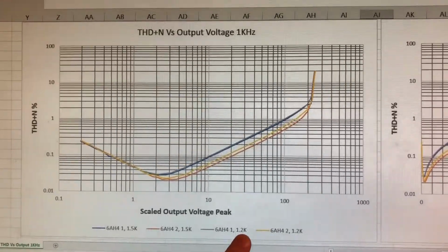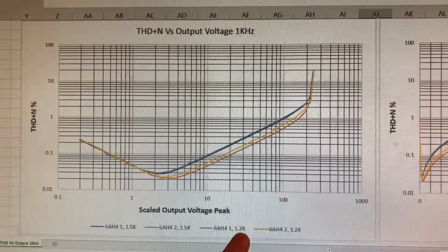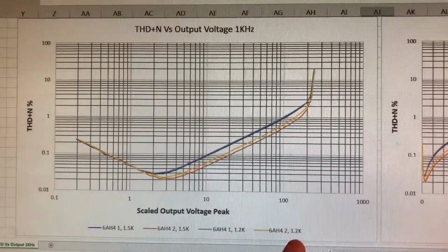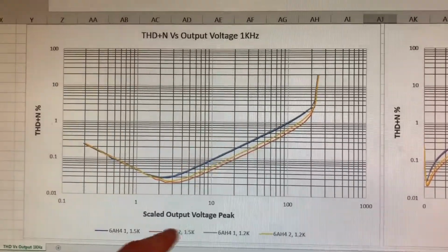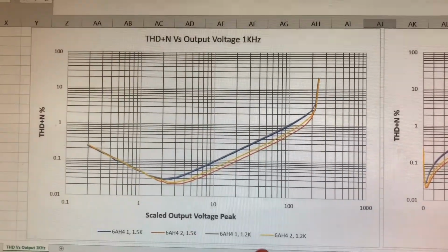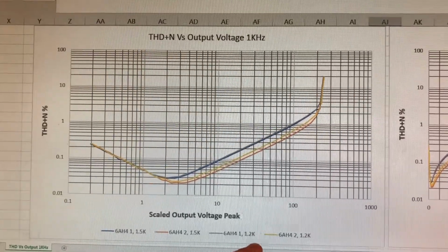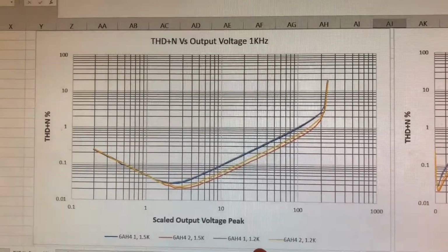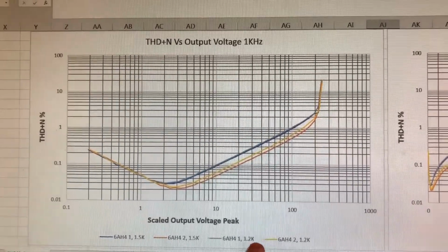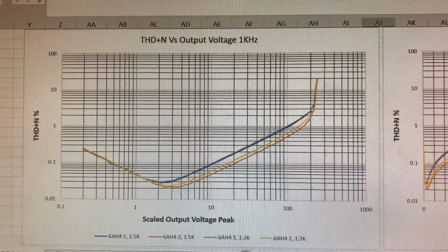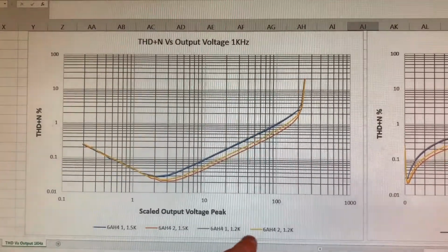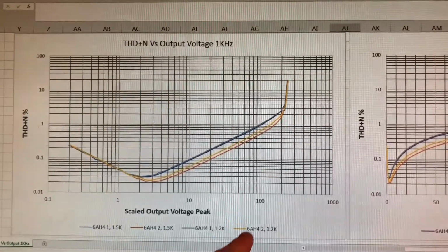substituted in our cathode resistor for 1.2 k ohms, and then recentered the bias, which gave me now about a 20 milliamp operating point. So a higher operating point compared to the 1.5 k ohm resistor. And that 20 milliamps gave me a 24 volt bias across this 1.2 k resistor, and was the best or very close to the optimal center operating point for the second operating point.